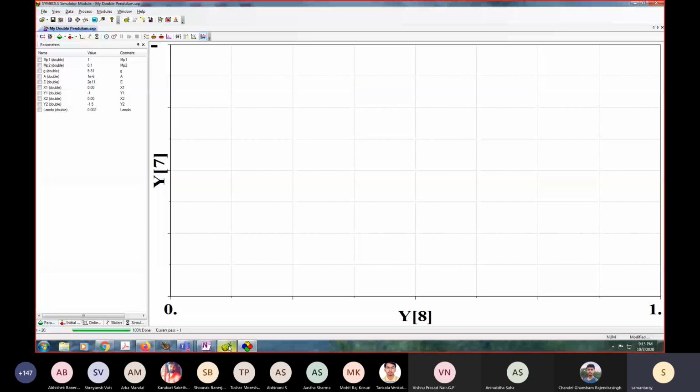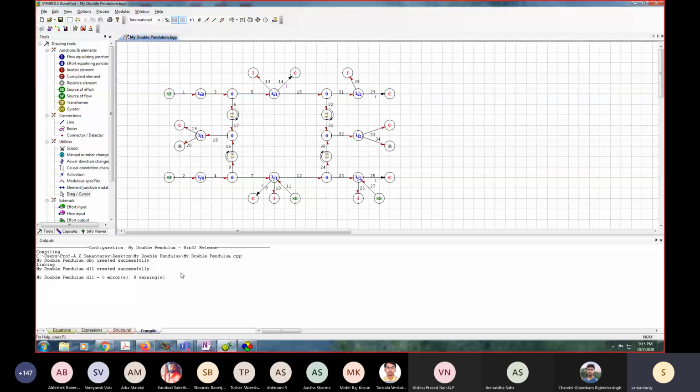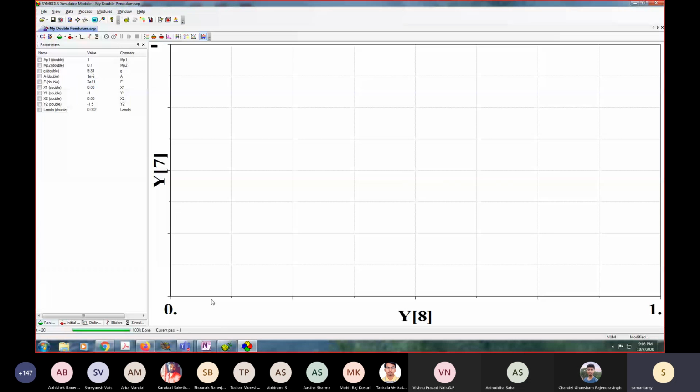So what I will do is I will push the big mass in the X direction with a certain velocity. I will give that as a momentum initial condition to this mass at bond number 13. So I give momentum P13 as the initial condition. Whatever velocity I want to give the mass is its momentum. The mass incidentally is 1, so whatever velocity, that is the momentum. So for P13 I will give a push. Let's say I push it at 5 meters per second.